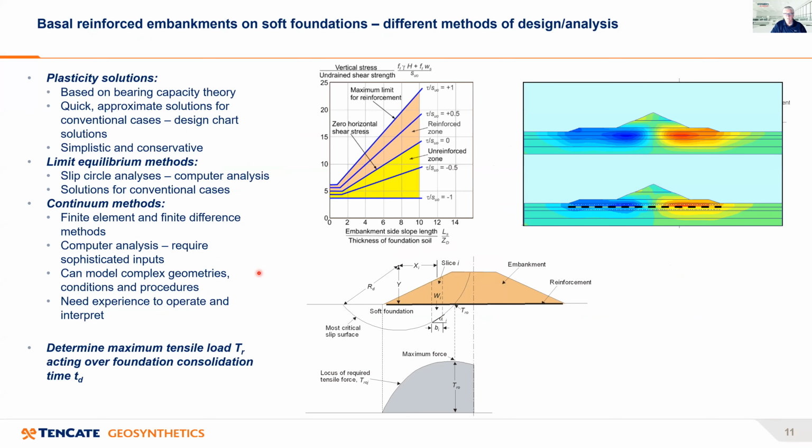Now, there's a number of methods we have available to us today to enable us to analyse and design embankments on soft foundation when it comes to determining the maximum tensile loads in that basal reinforcement. Generally, the solutions break down into three types of solutions. The first one here I've listed are plasticity solutions, and these are simple bearing capacity type solutions, which I spoke to briefly earlier, utilising bearing capacity theory.